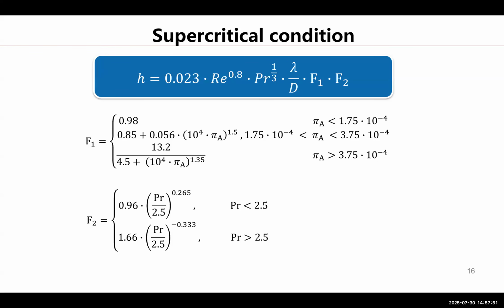Thirdly, the correlation should cover both the normal heat transfer behavior as well as the case with strong heat transfer reduction, as about 50% of the test points in the present experimental data bank may show strong heat transfer reduction. Sometimes we call it heat transfer deterioration.